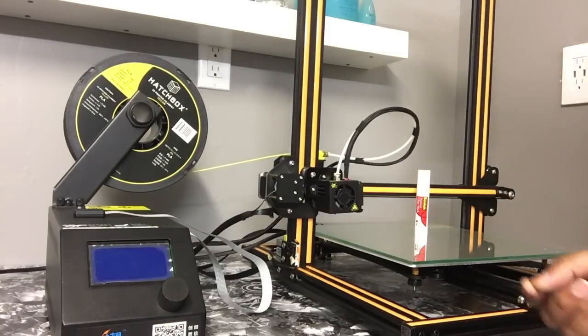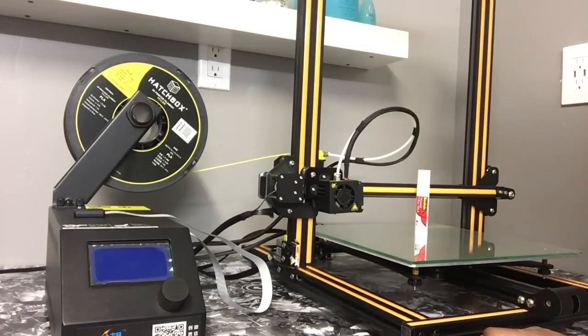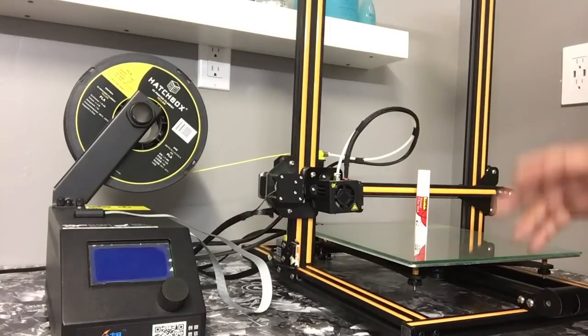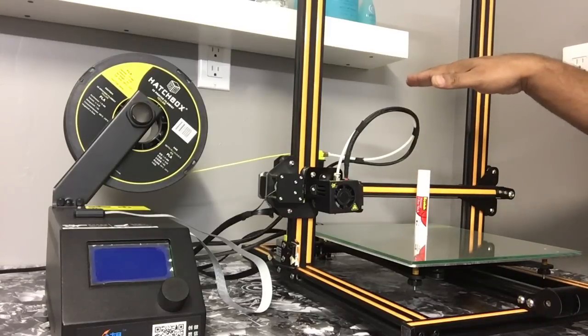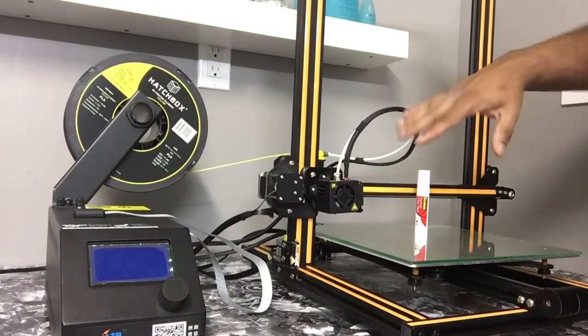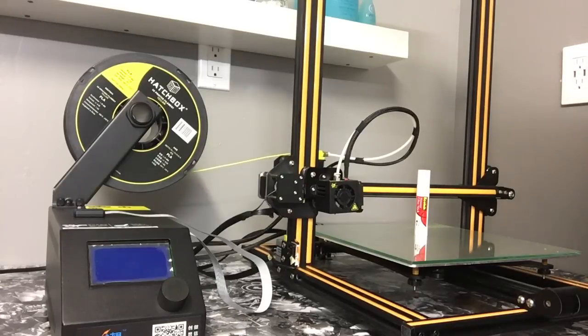I would recommend anything 6 hours or plus time-wise, level your bed. If you've just done one and you're starting a new one, level your bed. Because you don't want it to get about this high and then just topple over or be at an angle or slanted and have those imperfections.